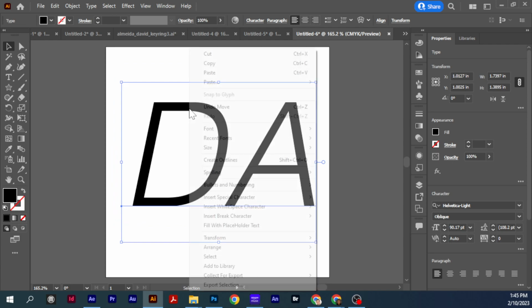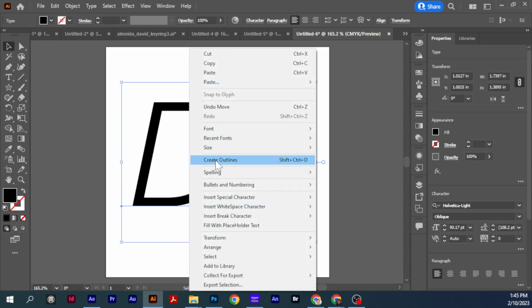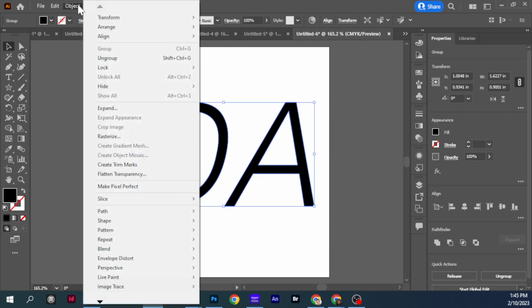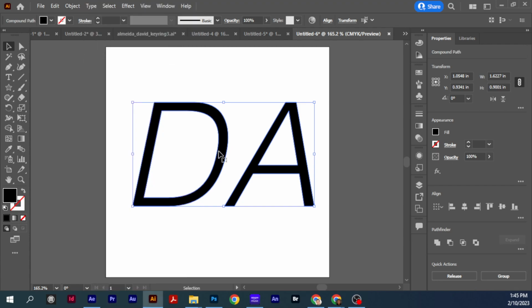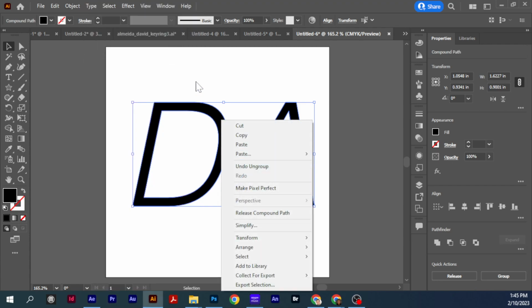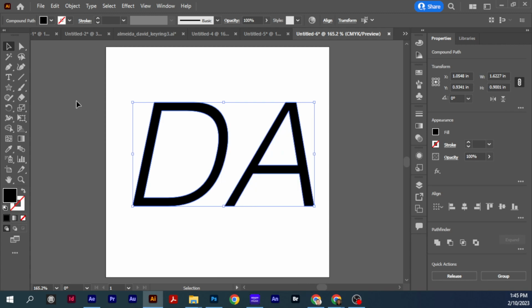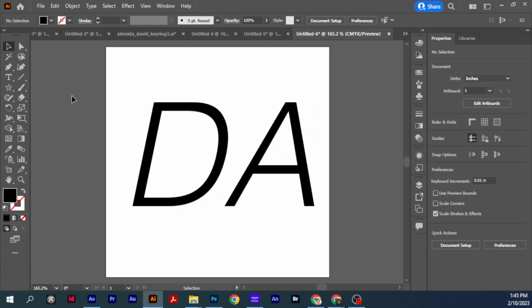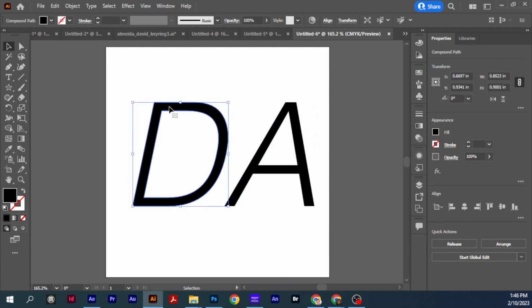And voila. Okay? One thing you want to do right off the bat is get rid of the font and make it a shape. Right-click, create outlines. Go to Object and Ungroup, or you can also right-click and ungroup. All right? Click on Nothingness. What I mean by nothingness, somewhere where there's no graphic, so the gray area of your interface. That allows you to grab individual items.